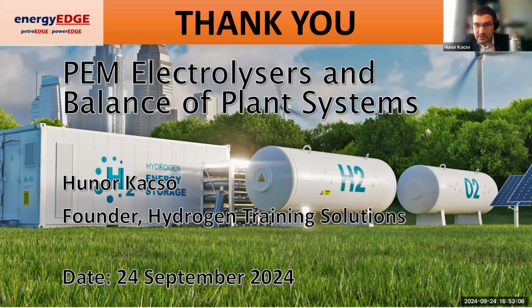Lifetime of a PEM electrolyzer in comparison to an alkaline electrolyzer. Great question. Nobody knows. This is actually a really good question. OEMs typically all tell us that their system will last for 80,000 hours. Show me one large-scale PEM electrolyzer, in the megawatt scale at least, that has provably been running without a stack failure and without any major failure on the balance of plant for 80,000 hours. You cannot show me one, and if you do, well, you just can't.